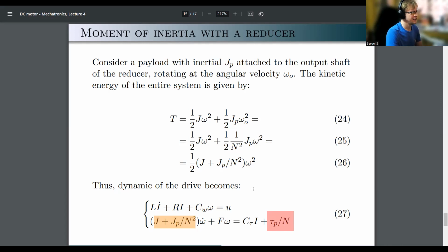than internal torques. So, for example, this friction force, which may be small, negligible, but because it doesn't have a reducer in front of it, it acts directly and it is potent, while the outside forces would be much less potent, depending on how big N is, right? So this is, again, the situation. And now I guess you can even see why we like reducers, why we use them so much, right?